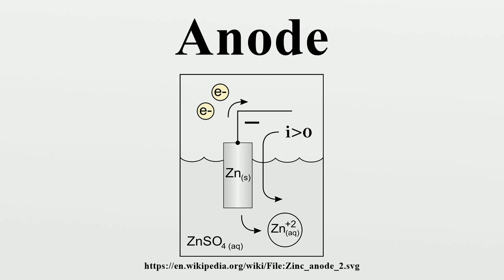In a diode, the anode is the positive terminal at the tail of the arrow symbol, where current flows into the device. Note: electrode naming for diodes is always based on the direction of the forward current, even for types such as Zener diodes or solar cells where the current of interest is the reverse current. In a cathode ray tube, the anode is the positive terminal where electrons flow out of the device, i.e., where positive electric current flows in.